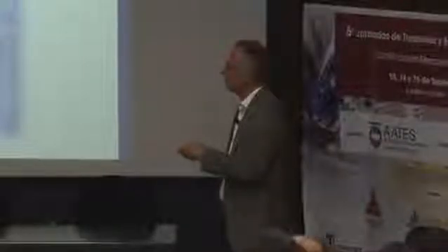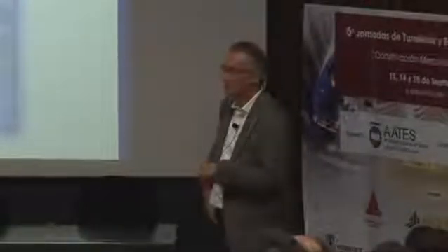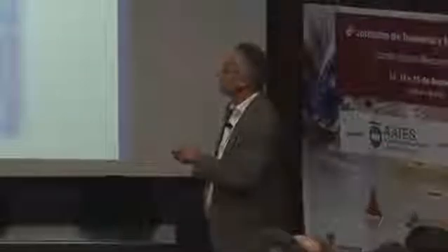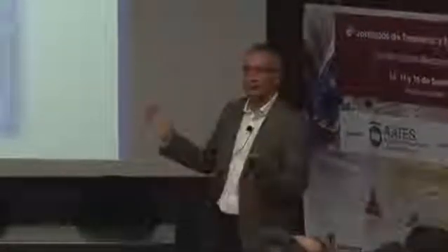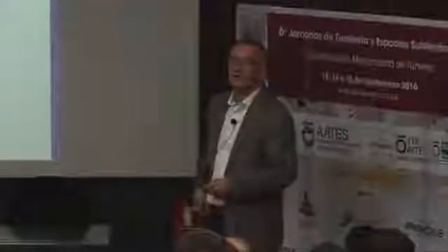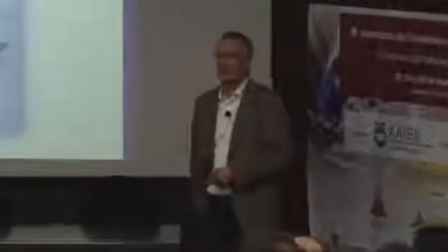Here's just a view. Opened the door with artificial soil. So that was the situation as you have seen before on the slide, where you practically had immediate connection to the surface. There it was completely sealed off. You had here an open face, and you could even start hand excavating. This is just behind the cutter head here, and using hoists, you could start repairing your cutter head, changing the tools. So with that, it's a very controlled manner, and up to now, typically you get every TBM repaired under the worst conditions.